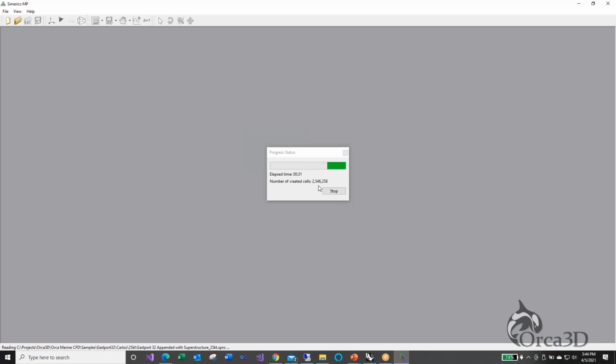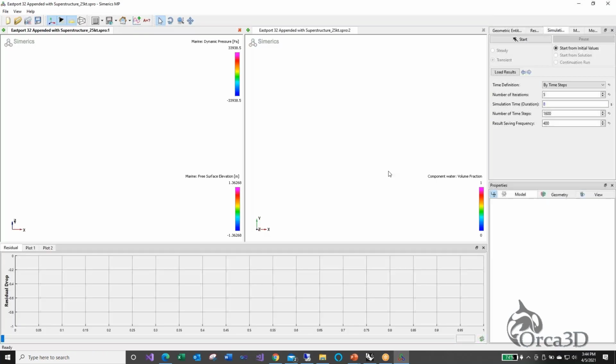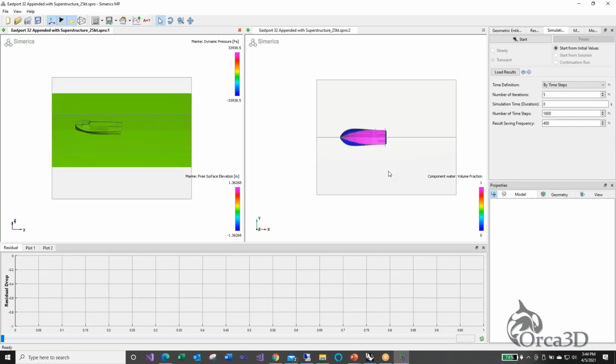Typically for CFD analysis, meshing of the fluid domain is one of the more time-consuming and difficult parts of the problem. Part of that is because while you may be familiar with meshing in a CAD program like Rhino, meshing for CFD is really an order of magnitude more complicated. It's not a 2D problem like CAD surface meshing, where you're breaking up a surface into little quads and tris. Here, you're breaking up a fluid volume into little cells. You can think of them as cubes or bricks, blocks of fluid. We're breaking a volume into smaller volumes in order to be able to solve the problem.